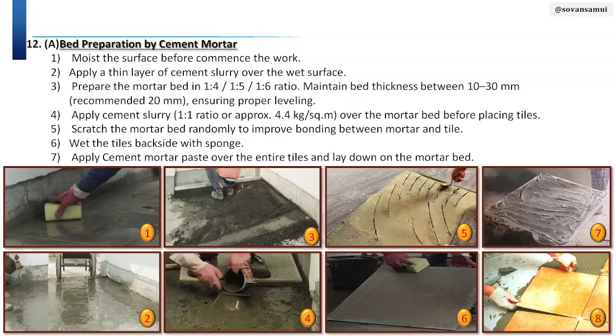And before tiles laying, the tiles' backside should be wet by sponge. You can see the image number 6, and apply a cement mortar paste over the tiles, and apply the bed.